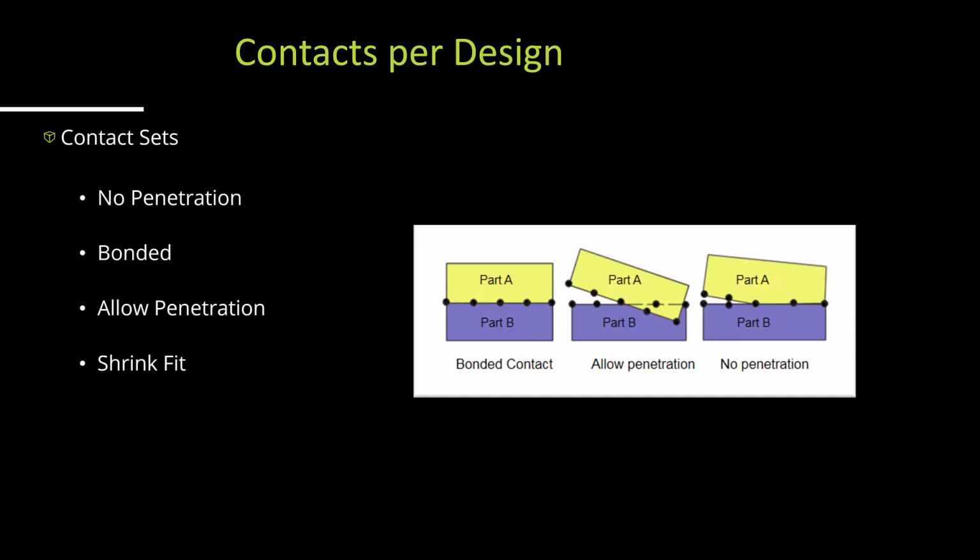Don't worry too much about these faces that are technically interfering with themselves. Likewise, if you run it with allow penetration, you may force that penetration through the other surface so far that you'll get very inaccurate results, and you'll be breaking physics within SOLIDWORKS, which is fun, but not so helpful for design work, right? And virtual walls, I kind of spoke about that earlier.